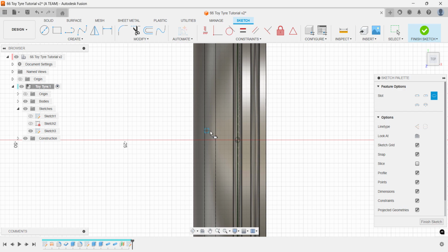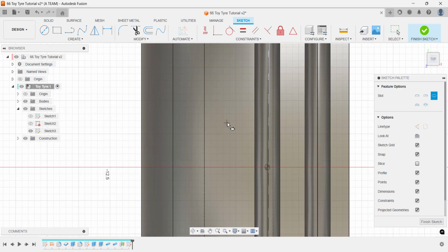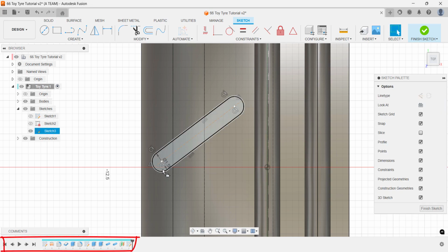in your toolbox. The positioning doesn't need to be perfect. Let's create something, and if the result isn't what we want after adding the 3D feature, we can always go back in the timeline and update the sketch.